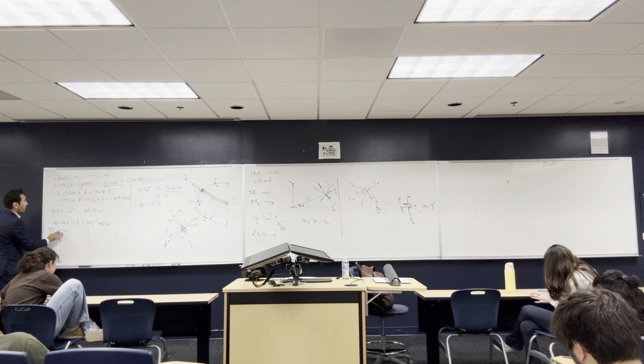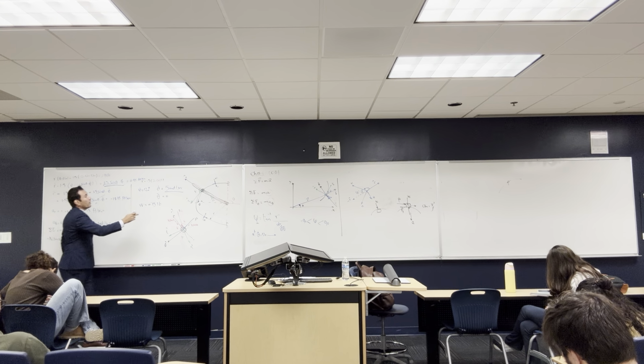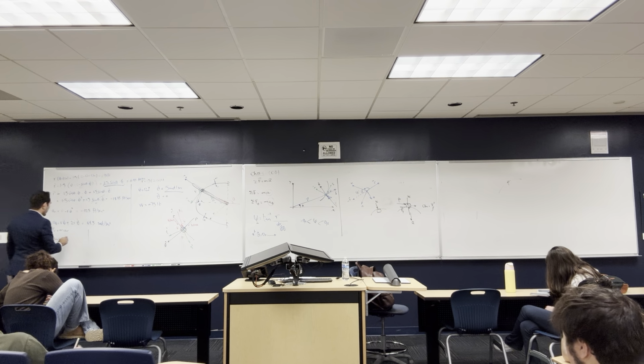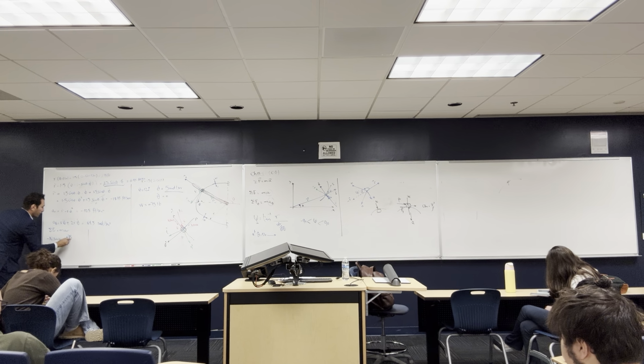And then I multiply by the mass. I already gave you the weight is 0.75, so I can put here 0.75 over 32.2 because I need to convert from weight to mass, multiplied by AR, which is negative 112.5.